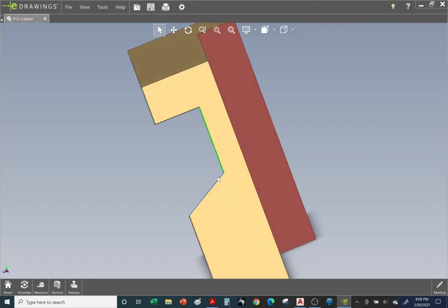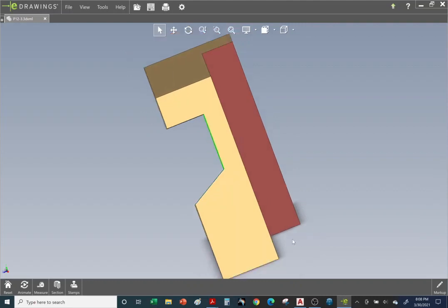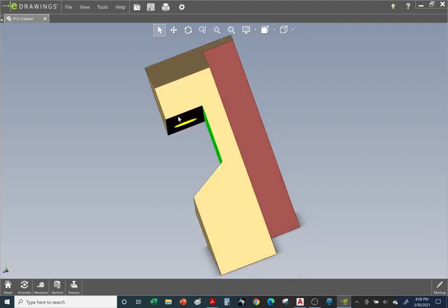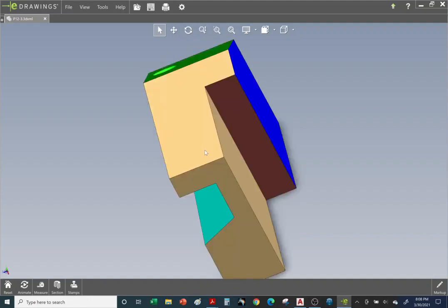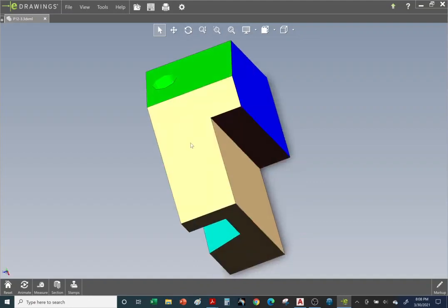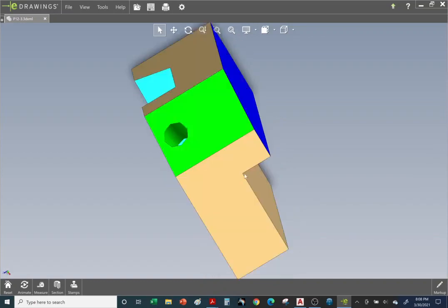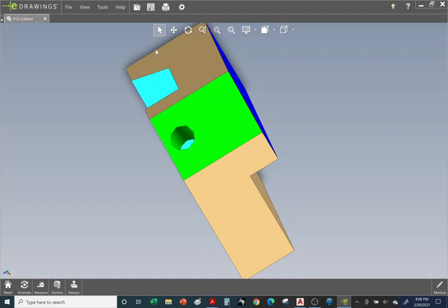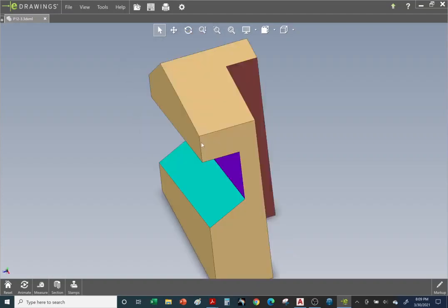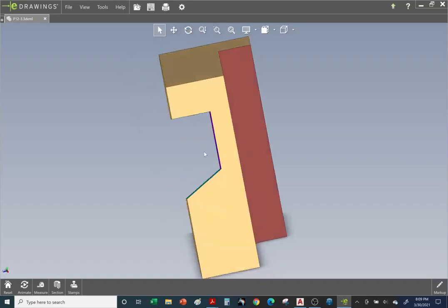So it looks a little different, right? As you can see, the bottom here looks different. And we do have the hole, right, going through, which we cannot see. We can't see the hole from this perspective, so we need to draw it, exiting at the bottom. Okay, and we need to draw these lines, I believe. Then we have hidden lines going across that we cannot see. So we need to draw this edge as a hidden line and this edge as a hidden line from this perspective. Right? So let's go back.